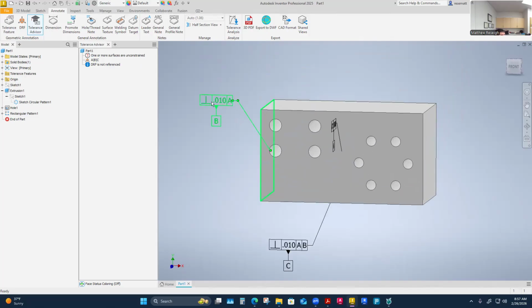but you can always get back in these, modify them, just double click. The other thing that I like is that it really only gives you the options that would really be available. So when I bring this drop down list, it's not like I have to pick from every geometric control there is. It's kind of minimizing, hey, based off A, these are really the things that you could try to hold from datum A. If they're not a selection here, then I probably shouldn't be trying to apply them potentially. Except I question why I don't get straightness right off the get-go. So there are some things that I still need to dive into to wonder what, anyway.